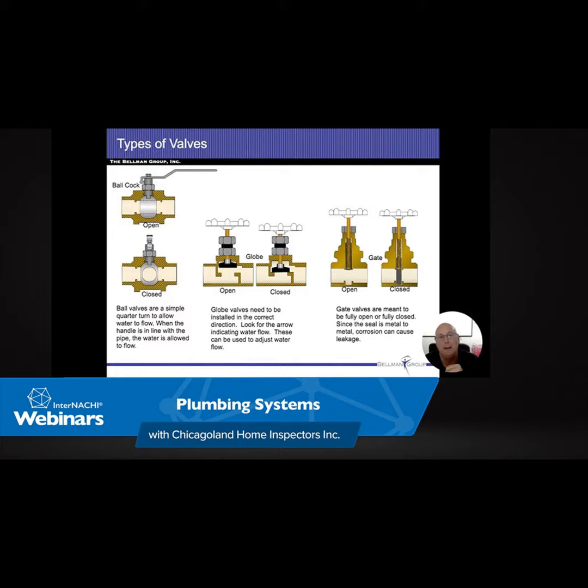Now, these centrifugal pumps can build on each other. So if I have a 500-foot well, I might have 4 pumps in there. All right, one is going to be all the way at the bottom, and then maybe every 100 or 200 feet, depending on the size of the pump, they're all going to kick on, and they're all going to take their turns moving the water up the line so we can get it to where we use it.